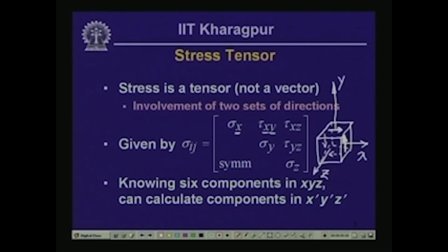So, the first subscript which is going to go with this shear stress is going to be x, and since this shear stress is occurring on a plane for which the outward normal is aligned with the positive y direction, the second subscript is going to be y. So, these shear stresses are going to be called tau x y. Similarly, you could have tau x z and tau y z when you consider the other planes.